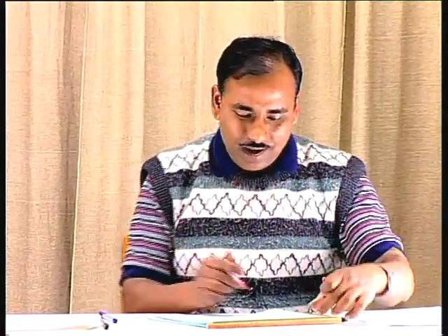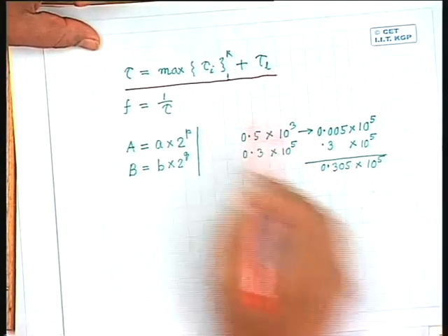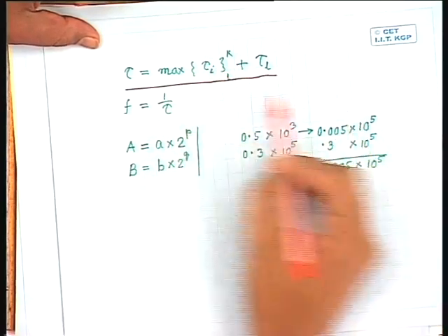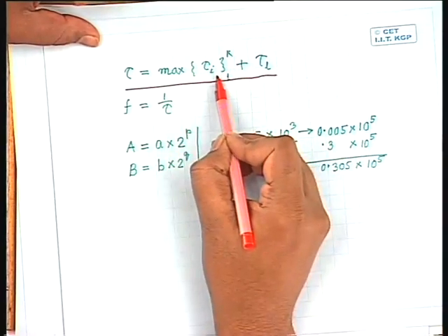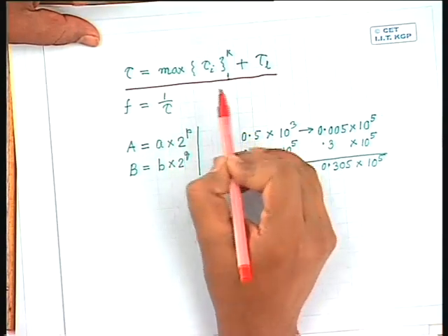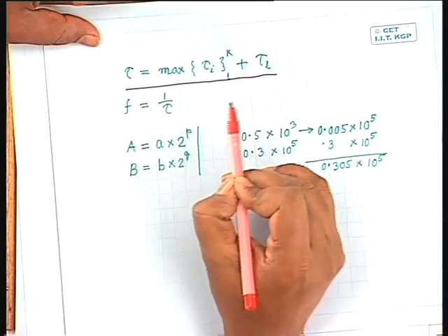And if you want to put the latch, in that case you have to decide at which frequency the pipeline has to operate. And this is the equation for that. So you find that the pipeline frequency, the rate at which the pipeline has to operate, depends upon the stage which takes maximum amount of time. And that is what is called pipeline bottleneck.